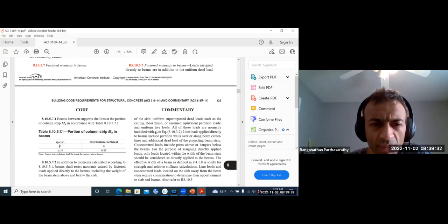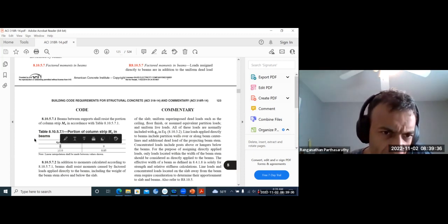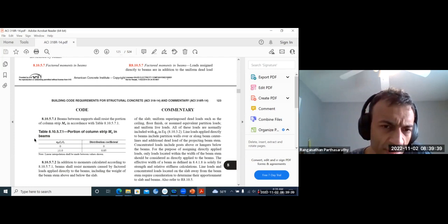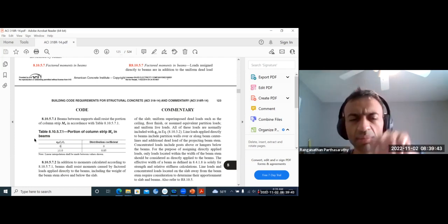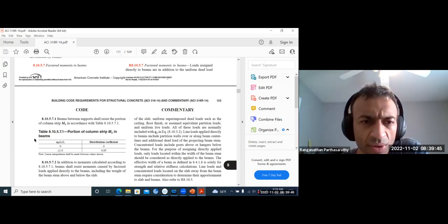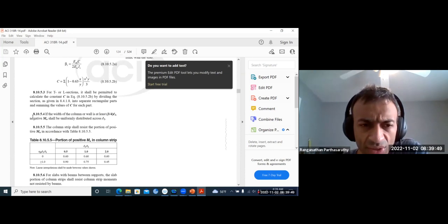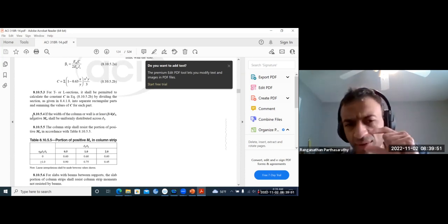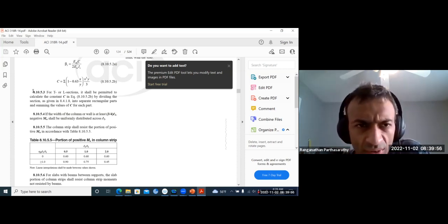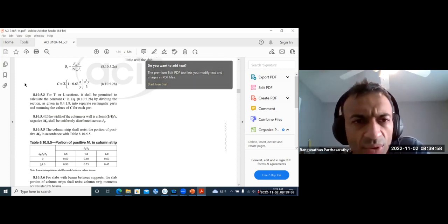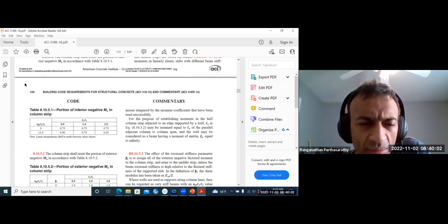That being 0 means it should be the case where there is no beam and everything is going to the slab. So in the column strip, all the bending is carried by the slab alone and nothing is carried by the beam. But still, as you said, there will be an effective beam there. If I clarify how to visualize this effective beam, it will become clear.